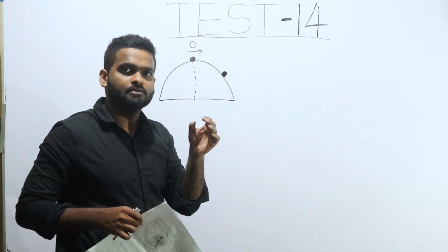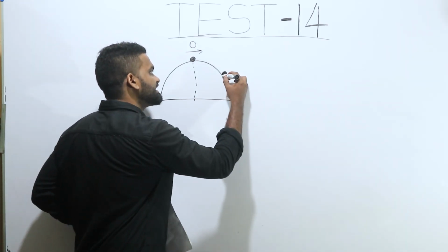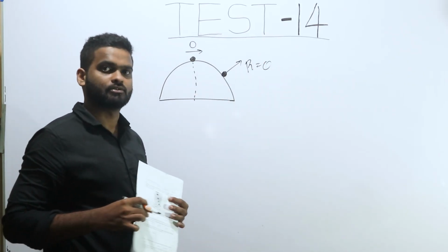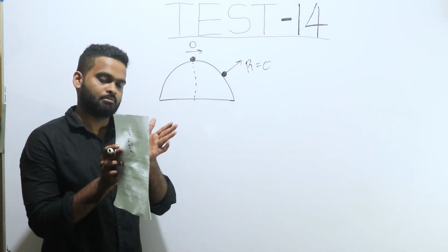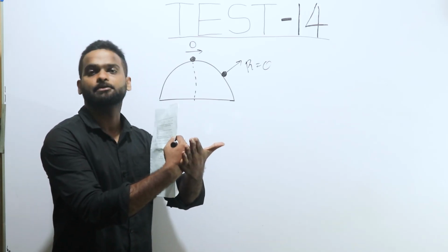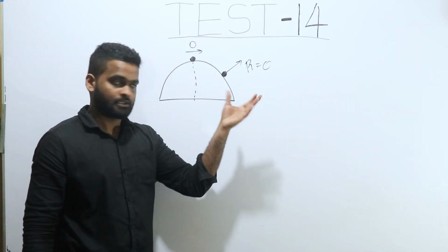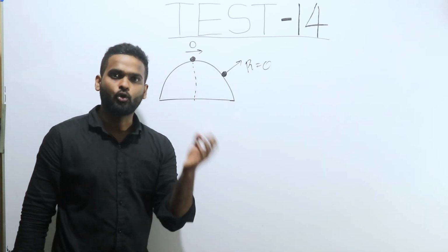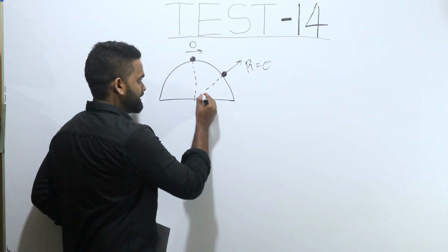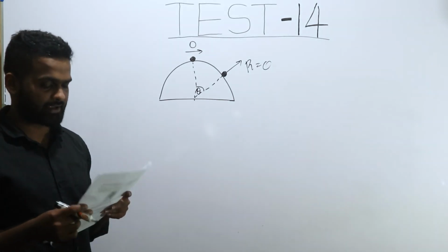normal reaction force becomes 0 at that moment. Once the contact is lost, normal reaction force becomes 0, because normal reaction force between objects is always due to contact. Whenever there's a contact between two objects, there's normal reaction force. If the contact is lost, what becomes 0 is the normal reaction force. So at this point, let's say this angle is theta at that moment. That's what they ask, the angle.